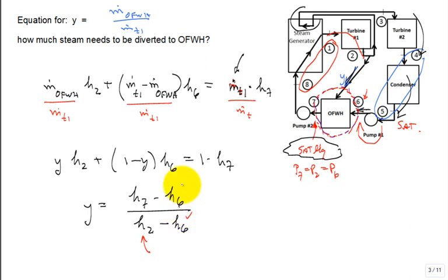And then what about H7? That's saturated liquid. Did I say it enough? Am I emphasizing that point too much? Am I boring you? It's saturated liquid at that intermediate pressure. That's the design intent. That's what helps the performance of the system, optimal. All right, let's press forward.